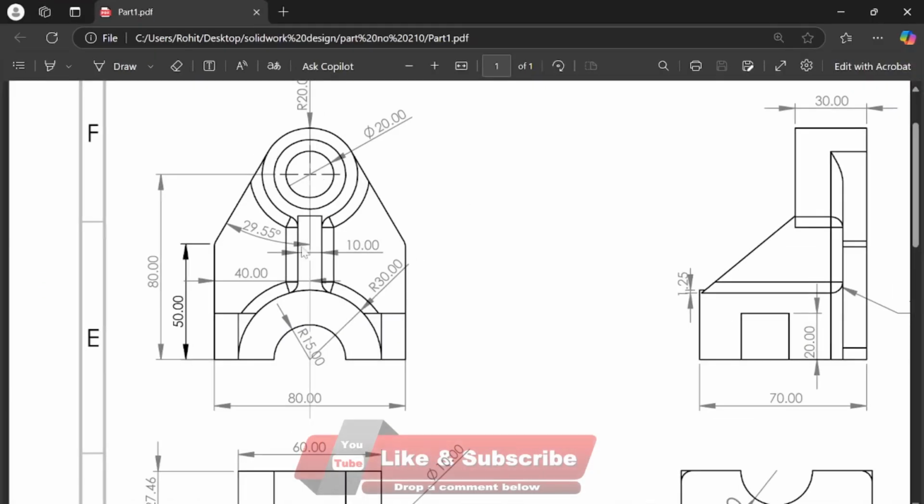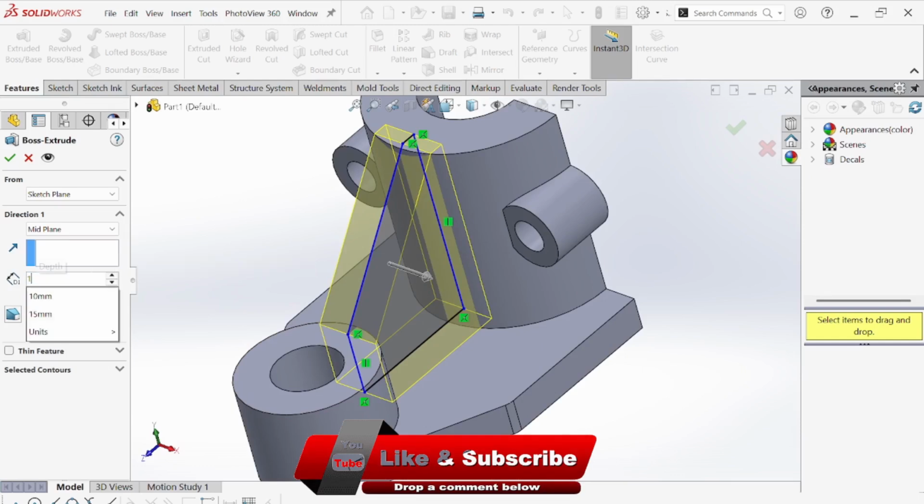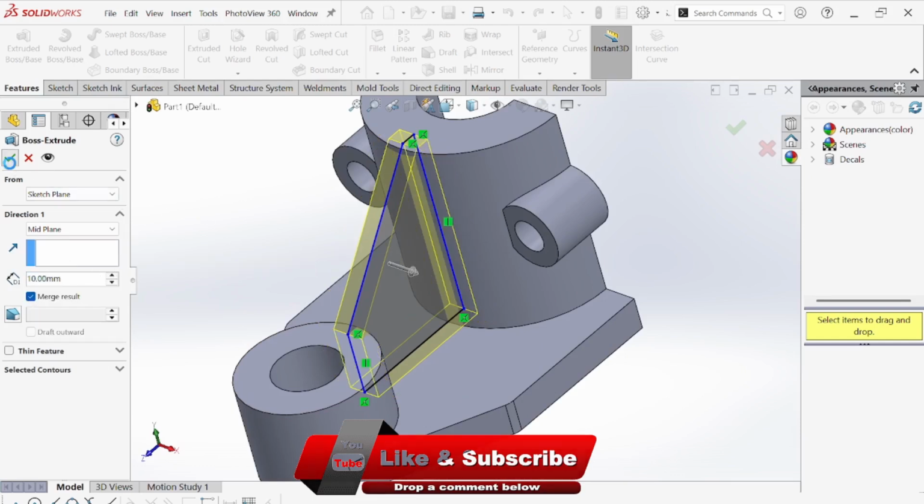And how much do we need to extrude? 10 mm. Yes, 10 mm. We need to extrude this thing 10 mm, meaning 5 mm in this direction, the left direction, and 5 mm in the right direction. Okay, so give dimension 10, make this one okay, and simply make this one done.